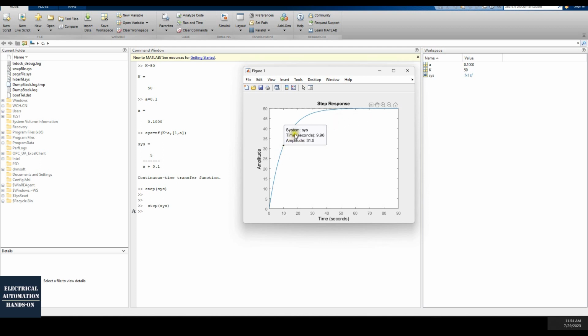When we give the step input to the equation after we have programmed it into the PLC, let's see if the output of the equation can react this way. For example, when the time gets to 40 seconds, if the result can get this temperature, almost this 42 degrees, then we can verify the result.